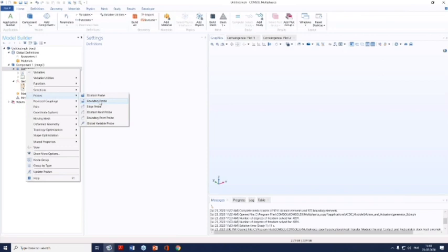The moving mesh technique is typically used, it comes under the deformed meshes. So for example, if you want to have relative motion between any two objects, it could be linear motion, it could be circular or rotational motion. In those cases, either the moving mesh is already incorporated in our inbuilt physics interfaces, like the FSI interface, wherein fluid structure coupling is done by incorporating the moving mesh interface, or the rotating machinery interface as I was showing you, wherein the rotation has been captured by means of the moving mesh interface as well.